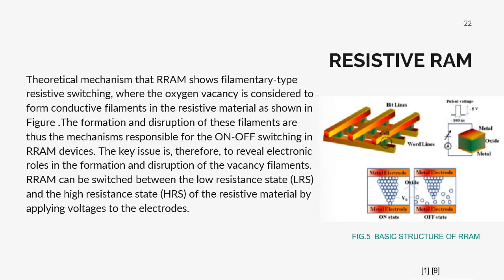The theoretical mechanism of resistive RAM shows filamentary type resistive switching, where oxygen vacancies are considered to form conductive filaments in the resistive materials, as shown in the figure. The formation and the disruption of these filaments are thus the mechanism responsible for on-off switching in